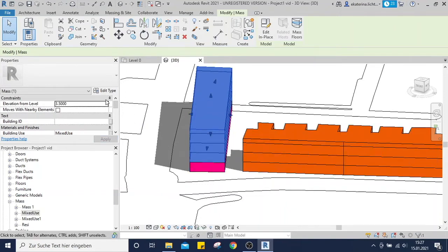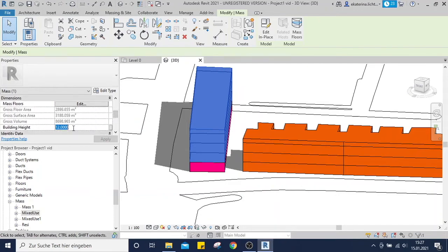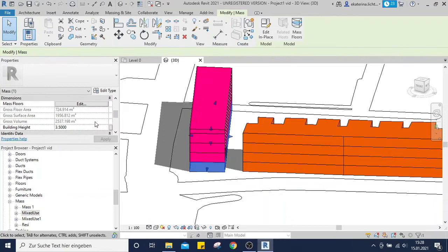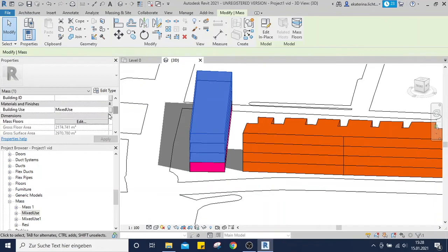It did. So if I wanted that to be 12 meters tall, we're going in 7ths, right? So 14. Really, this should be 14. So we have an even number if our floor height is 3.5. So we have 3.5, 7, 10.5, 14. So now this one needs to be 10.5. Nope, wrong one. This one needs to be 10.5 and it hovers. There we go. So we need to change the land use here, the building use to residential.